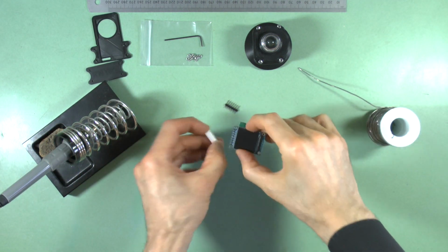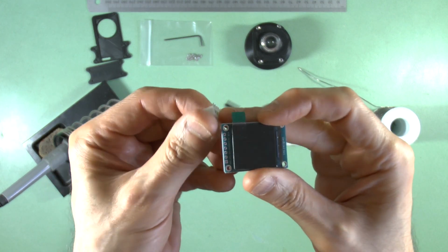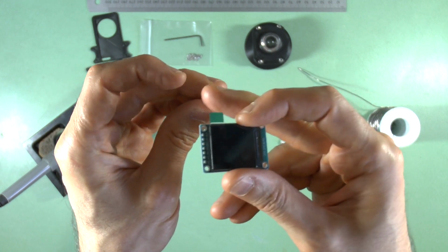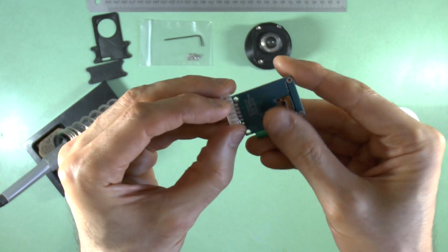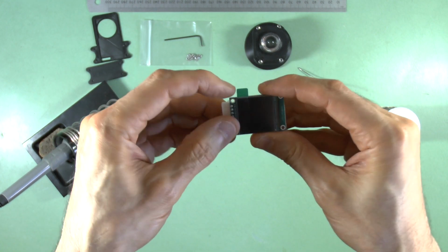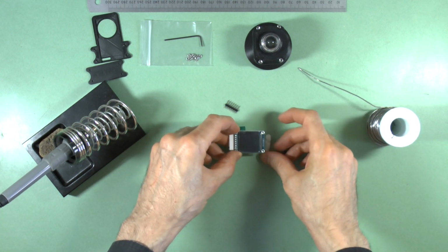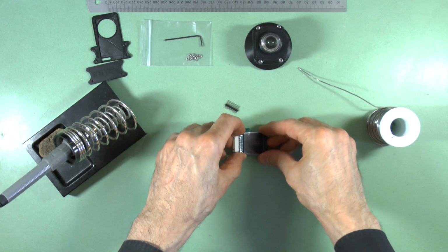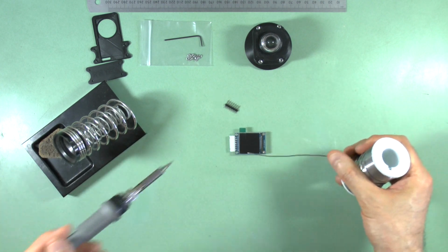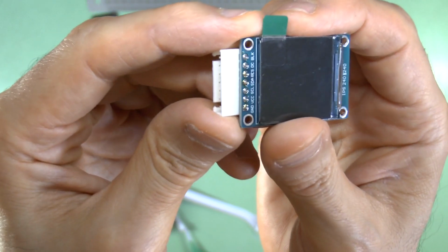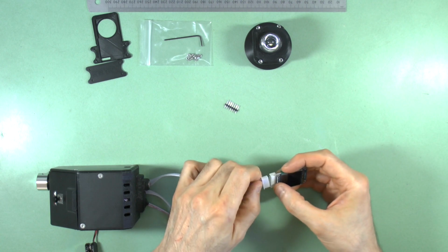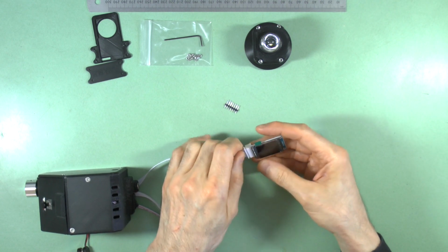Now solder the connector to the screen. I use a 7-pin JST-XH male PCB header with 90-degree pins as shown, rather than the supplied connector, because it ensures I connect the ribbon cable the correct way round each time, provided of course you connect the header the right way round at this stage, so ensure you connect it as shown. After soldering, test the screen to ensure it still works.